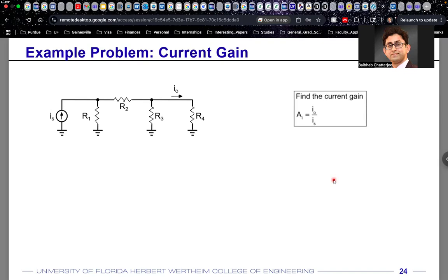So this is transconductance gain. And there would be a quantity called transconductance, which we'll be using heavily in this entire course when you get to MOSFETs. So transconductance will mean that you apply an input voltage and you get an output current.